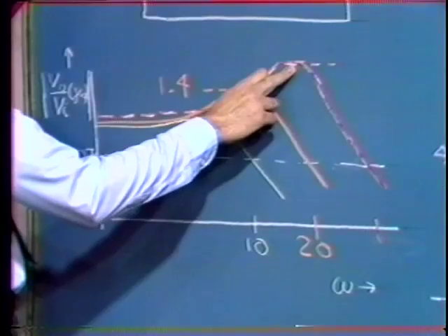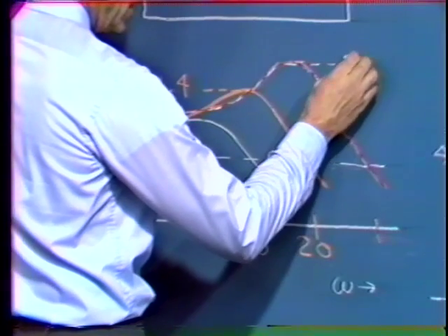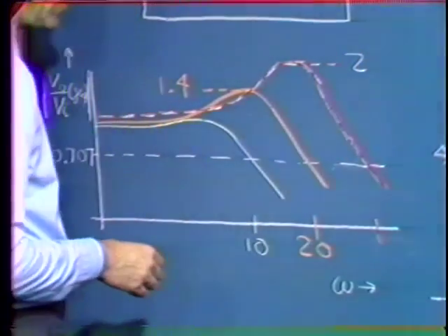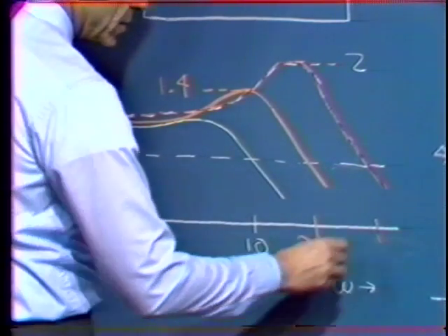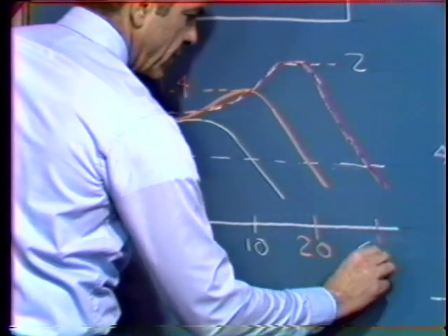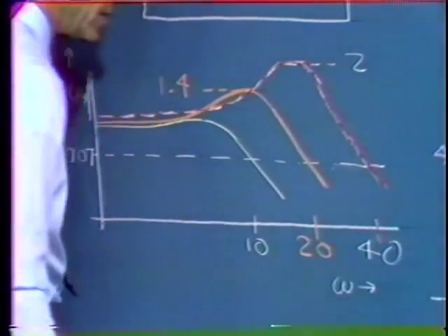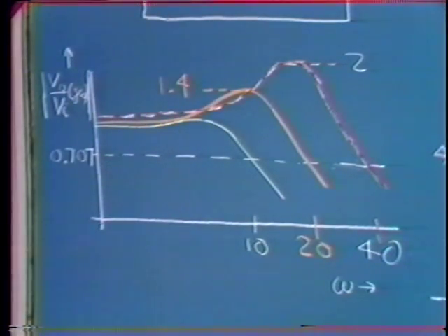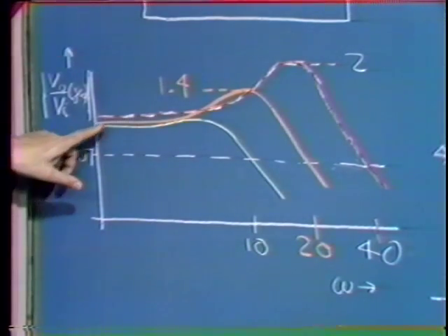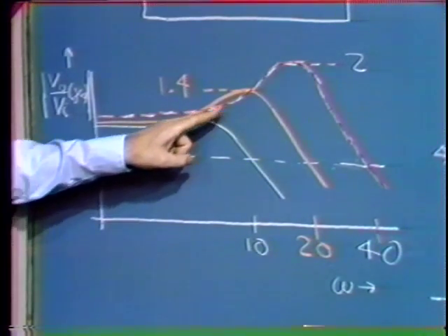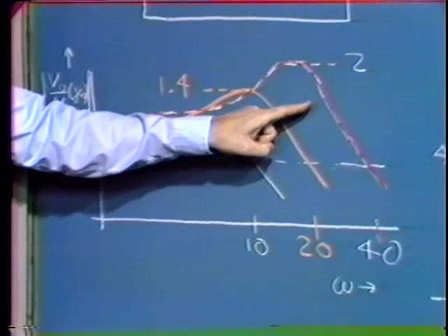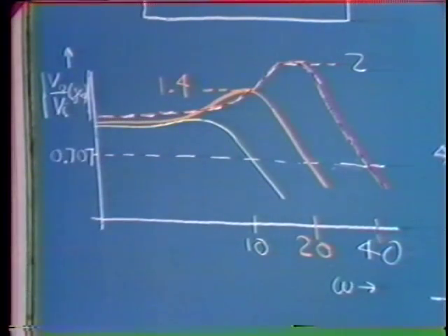We'd find that the peak magnitude is about 2, as we've seen from the Nyquist chart, and that the 0.707 frequency is about 40 or 45 radians per second, somewhere in here. So we can quite quickly, with the aid of the Nyquist chart, determine the closed loop transfer function of the system, and of course get a very graphic indication of the deteriorating stability as we go to larger and larger values for A0.